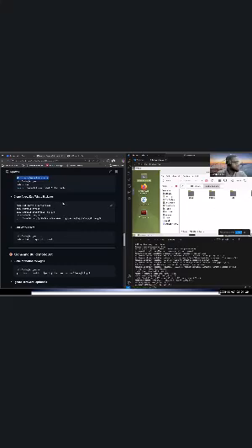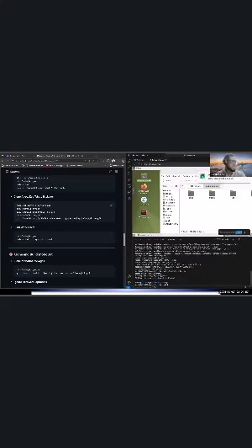So we've installed the teleop package. Next thing is to build the workspace. So just copy this and paste it, and symlink install. Symlink install means you can edit your code and the changes take effect. You can actually edit your code and you don't have to build again, right? So that's what symlink install does. I'm going to keep that in case anybody has any question.